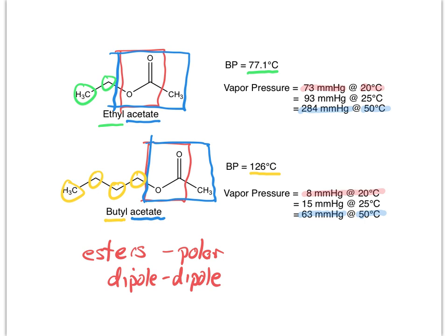And so we say that ethyl acetate is the more volatile. When we say something is volatile, we're talking about its vapor pressure, right? So in organic chemistry, volatile means it has a higher vapor pressure. And so at any moment in the vapor above our liquid mixture, we're going to have more ethyl acetate than butyl acetate, and that's what we're trying to use then to separate them.